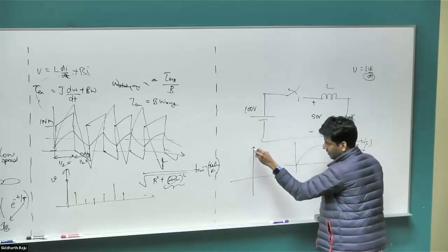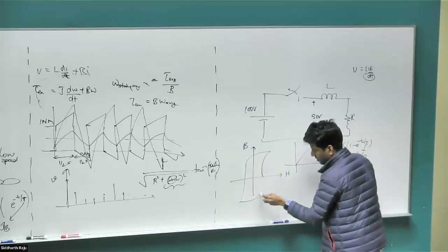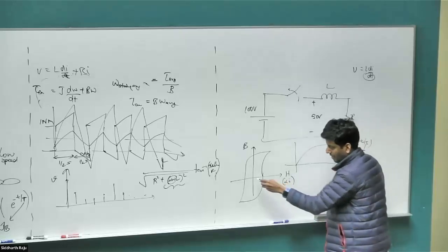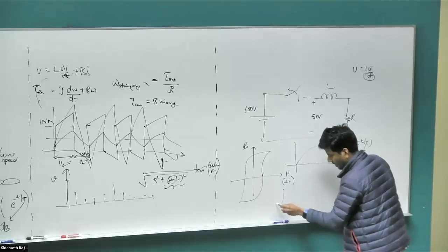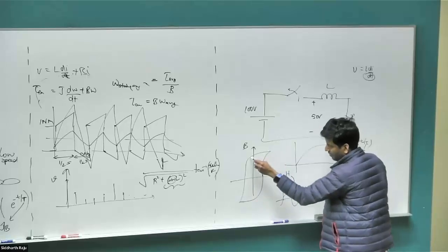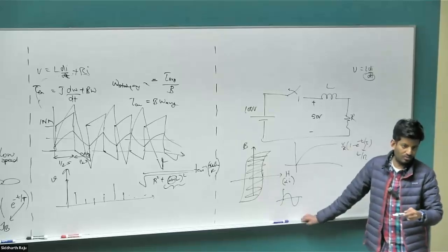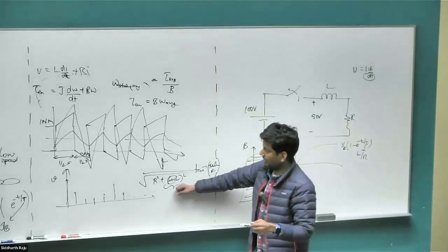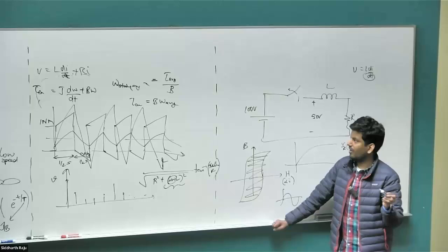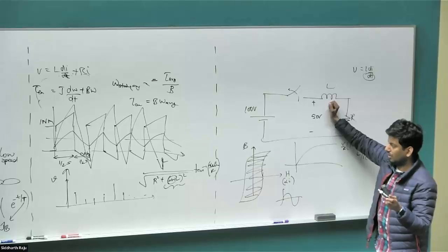So when we looked at our BH curve of our iron core, it has this shape. Right? So this is directly proportional to the current that we apply. And as we keep increasing the current, reducing it, so when the current varies sinusoidally, H varies sinusoidally as well, but the B does this loop, right? So whatever is the area inside this loop, that is totally lost, that cannot be recovered. That's the hysteresis loss. So whatever these harmonic components are, these are actually going to be lost as a hysteretic loss in your inductor. That is not recovered, that's not useful in any way, right? And it's going to start to heat up the iron core of your inductor. In addition, it's going to make your converter very lossy and inefficient.